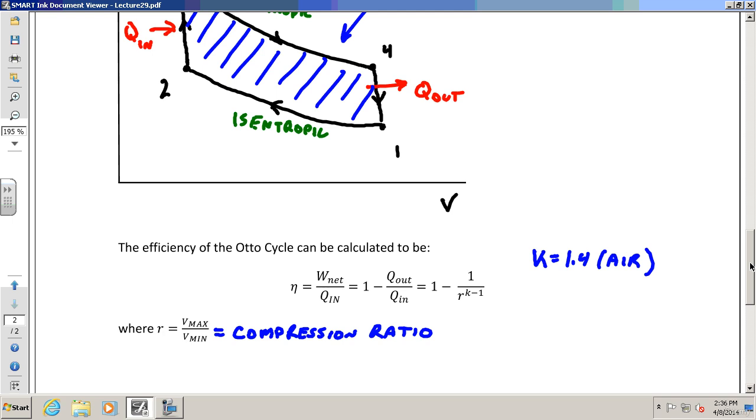All that is there for is to allow the vehicles to run at higher compression ratios and keep them from knocking. So if you don't have a vehicle that requires higher fuels, getting higher fuels in there won't help it any. The only thing that a higher octane fuel will do is keep it from knocking on the higher compression ratios.